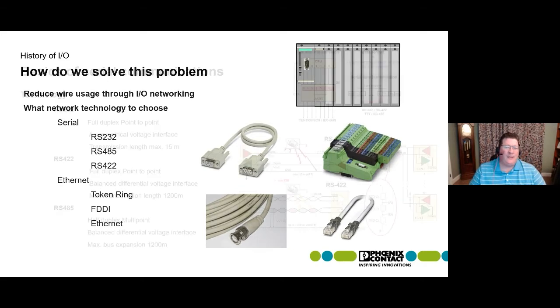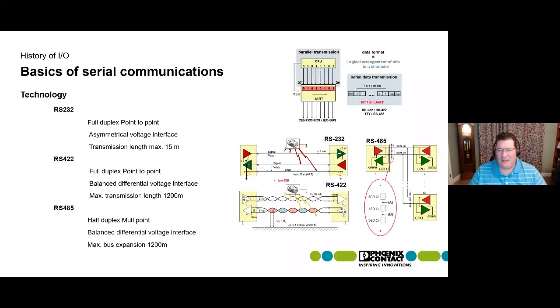So basically, all the PLC manufacturers went out. They all started looking at the serial communications as options. Step one is they just looked at, well, I'll just network my PLCs on a serial network and they can talk to each other. This was not cost effective. The processors are expensive. So they're looking at, well, we've got to simplify this. We've got to get the I/O cards and move them to the field. Not the processor, not the brain of the PLC, because that's the expensive chunk, but just the I/O cards.